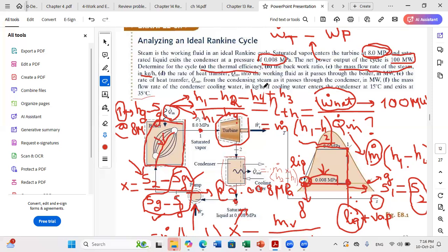And sometimes maybe, let's say, if you need to reach high temperatures of 70 or 100 degrees, you might not be able to use this cycle because maybe the mass flow rate will be really very small. So it depends on the applications that you have. If you just want to use water for swimming pools, 35 degrees is great. If you just reach 35, it's fine. But if you need to supply water for shower, you need a higher temperature to kill bacteria. Okay, so you need to select appropriate cycles.